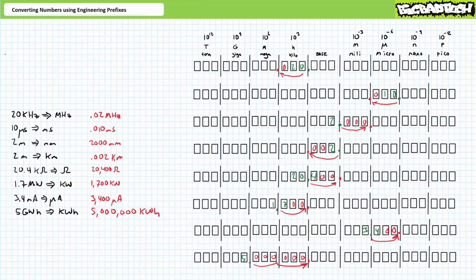In conclusion, this lecture took a look at conversion between different engineering prefixes. We learned there's a useful symmetry of 1,000 times between adjacent engineering prefixes, and by shifting the decimal point 3 steps to each prefix, we can represent numbers using different prefixes and still maintain equivalency. Remember to review this material as often as you need to really drive it home. Imagine how well lab will go if you know what you're doing.